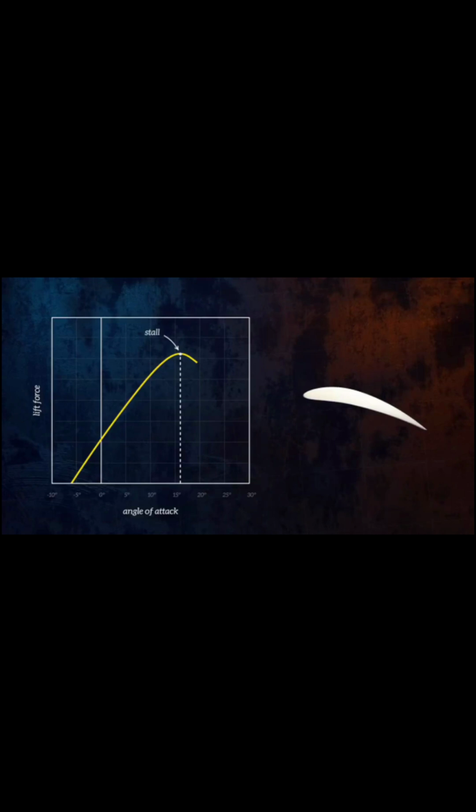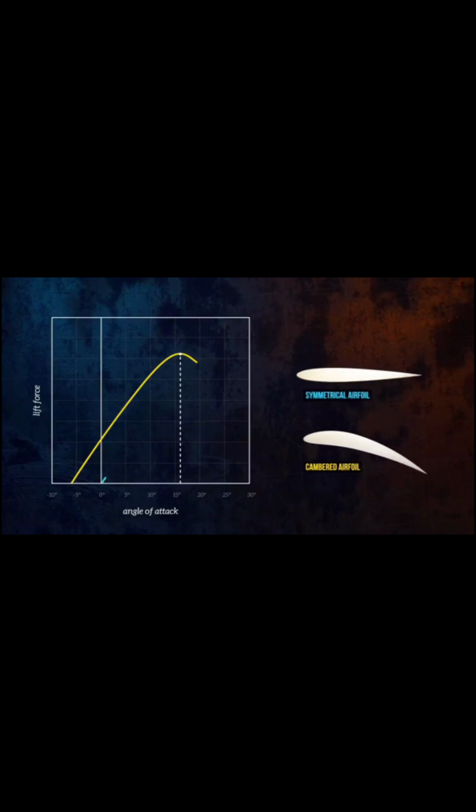Different airfoil shapes can have drastically different lift characteristics. This airfoil is cambered. If an airfoil is symmetrical, and so has zero camber, the lift force will be zero for zero angle of attack.